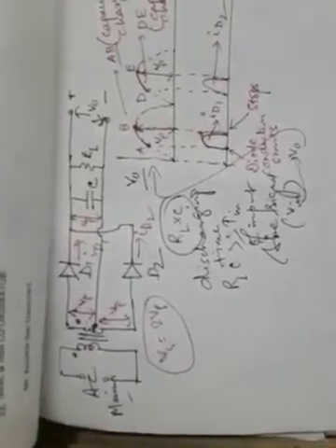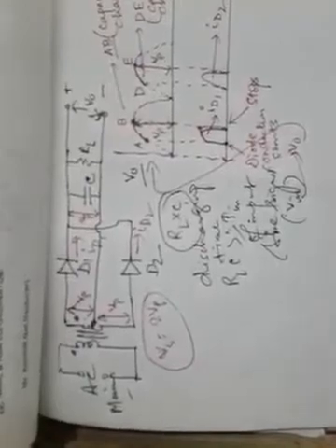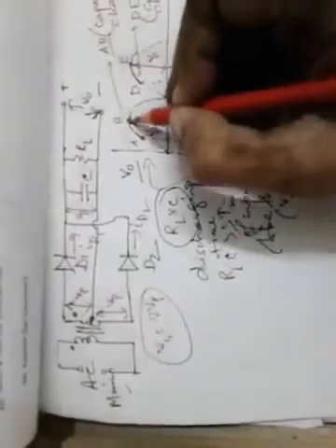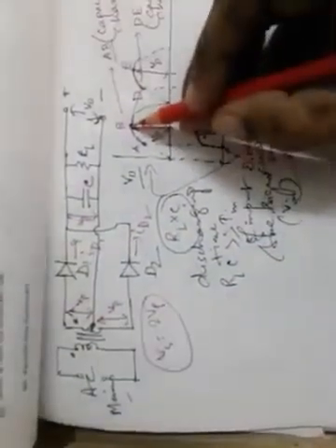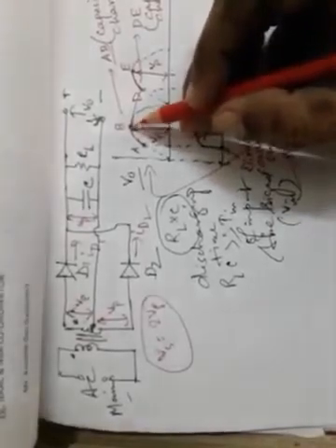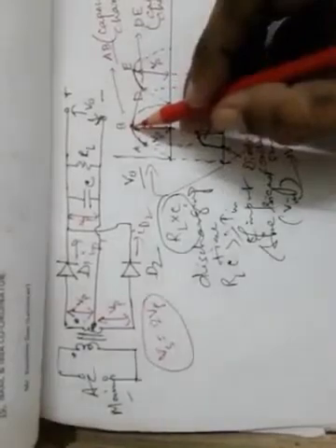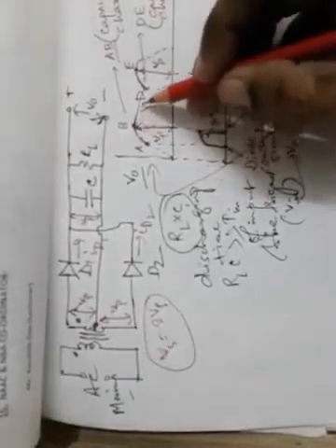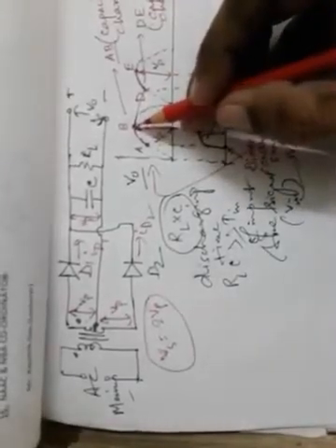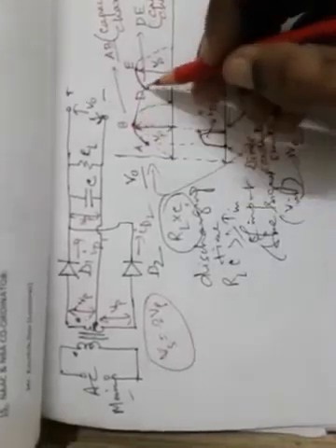So between these 2 points, that is between B and D, neither of the diodes D1 or D2 will conduct, and as a result there is no scope of charging of the capacitor C, and the capacitor during that period can only discharge. So during this period B to D, the capacitor will only discharge. There we will observe a little bit of dip in the curve, which will be an exponential dip or decline between the points B and D.